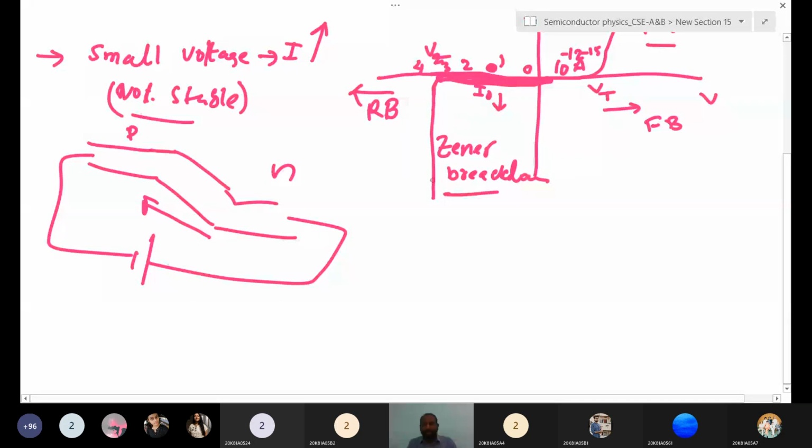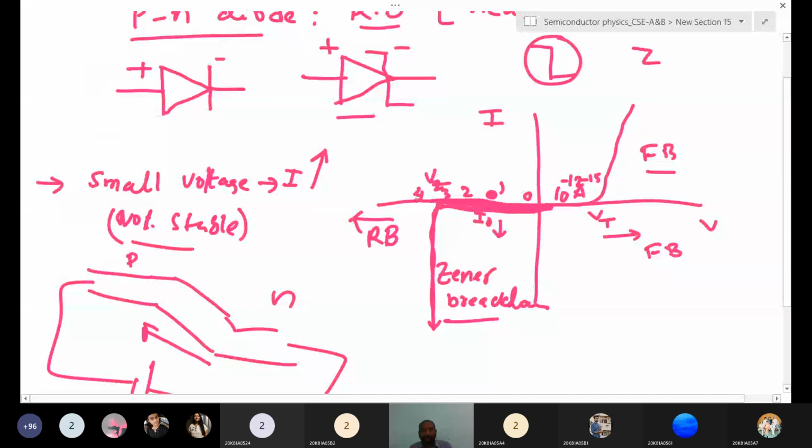A Zener diode is a simple PN junction diode. It operates in reverse bias condition. That is why we use it in reverse bias, for example in voltage regulators, or if you want to prevent damage to meters or test voltmeters. Even if you change the voltage slightly, the voltage should be stable. Then you can see how much the current is changing.